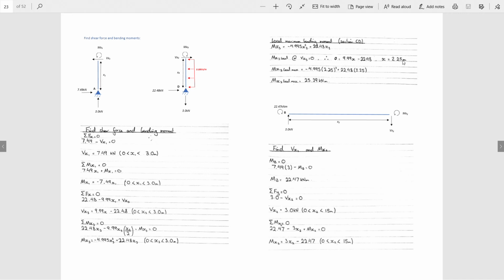Now, we can see that this is not halfway. The reason for this is because we do have another member here, and loading just doesn't work in this way. So if you apply loading this way, it doesn't just apply that way. So we substitute in our value into this, and we're spat out with our answer. Right, we sub in that value. We sub that value back into our shear force, our bending moment diagram. And then we continue on the calculations.